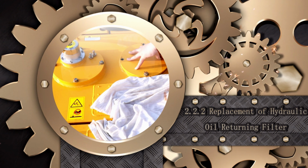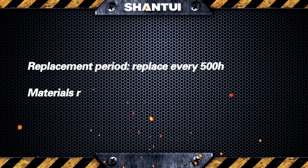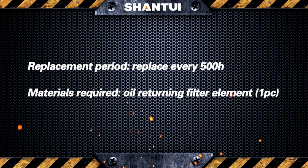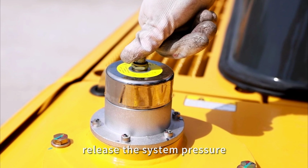Replacement of hydraulic oil returning filter. Replacement period: replace every 500 H. Materials required: oil returning filter element, 1 PC. Replacement steps: 1. Release the system pressure.